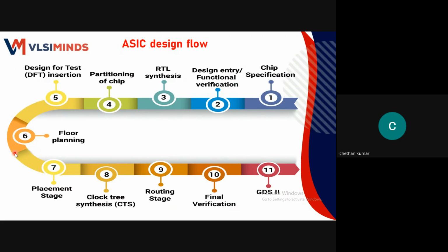So the design verification team will come, and then the synthesis team will come, and then partitioning the entire chip or the entire IC into different parts, because the entire IC cannot be taken at the same time. The partitioning makes it easier to test the chip at different levels, so that will be done at the partitioning of the chip. And then the DFT insertion will come.